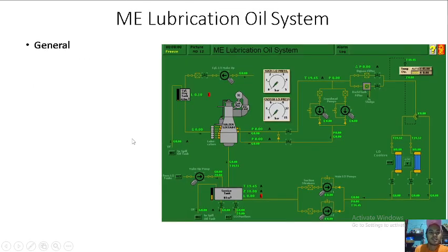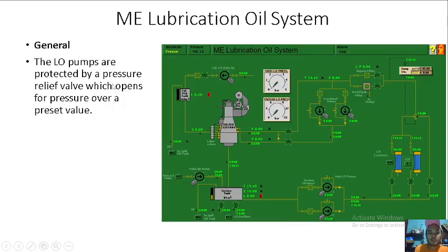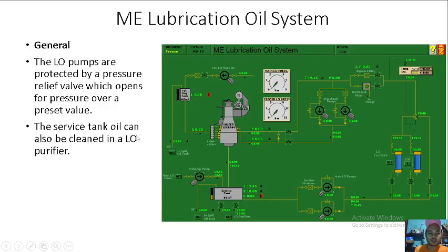Okay. And then the lube oil pumps are protected by a pressure relief valve in here, which opens for pressure over a preset value. So if there is overpressure, there is a protection to prevent damage to the pump and to its motor. The service tank oil can also be cleaned in a lube oil purifier here. So we can open this one, inlet, suction and discharge of the lube oil purifier. So it is continuous purification 24 hours.